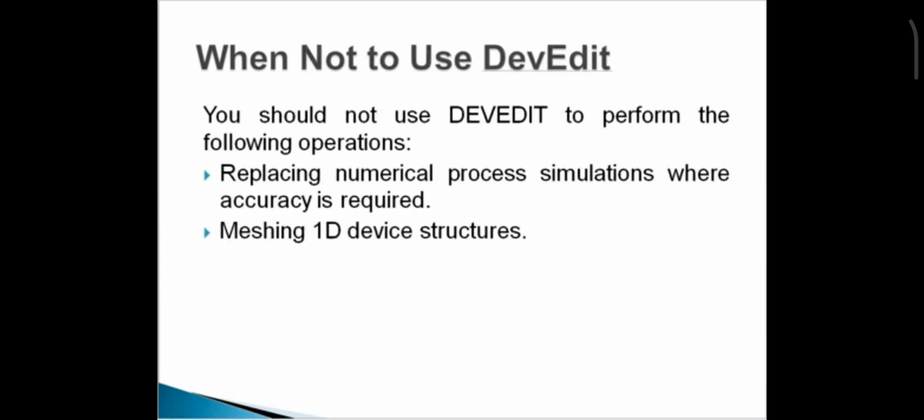When not to use DevEdit? You should not use DevEdit to perform the following operations: replacing numerical process simulations where accuracy is required, and meshing 1D device structures. We cannot use DevEdit on 1D device structures.